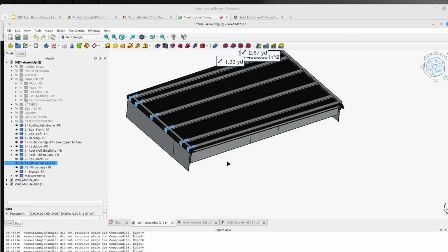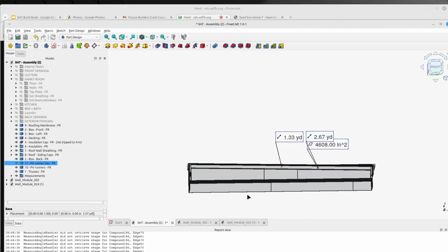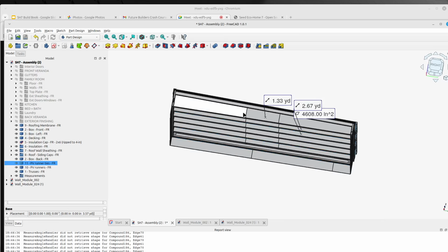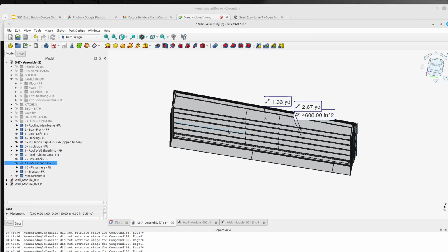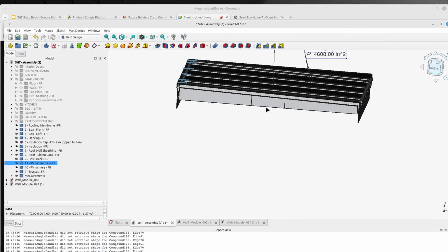Okay, so this is what we will build. We like the idea of the tapered trusses. That's definitely an idea. And as I said, maybe you don't want to build that, or you want to just use standard lumber, you can use 1x12s that are 20 foot long. They're still reasonable in price. But then you have to add the taper mechanisms so you get drainage, which we did last time, just using tapers that have about a 4-inch, I think it's 6-inch rise over the entire 20-foot length of the roof. That's basically it.